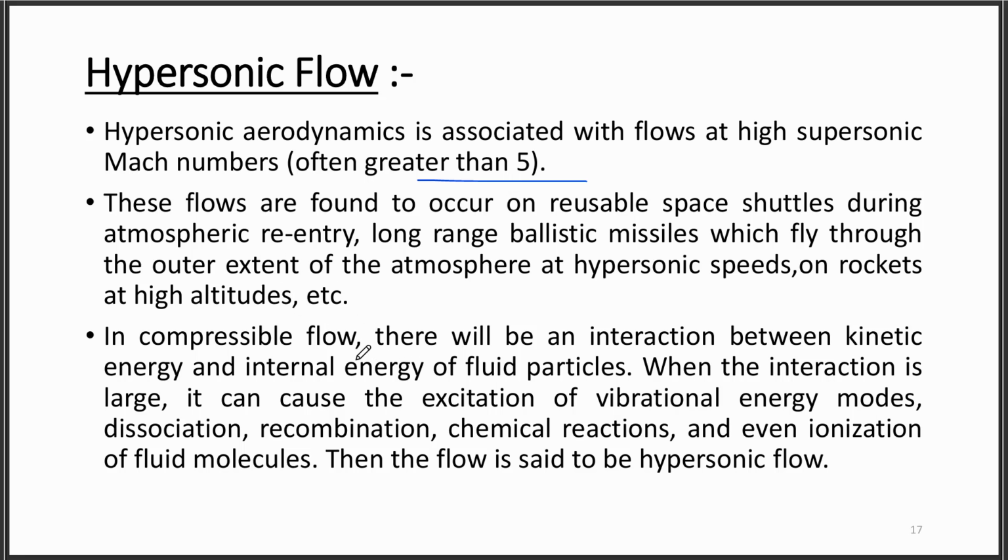So in compressible flow, what happens is that there will be an interaction of kinetic energy and internal energy of the fluid particle. When the interaction is large, it can cause the excitation of vibrational energy modes, dissociation, recombination, chemical reactions, and even ionization of fluid molecules. Then the flow is called hypersonic flow.